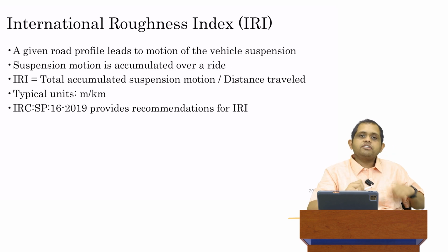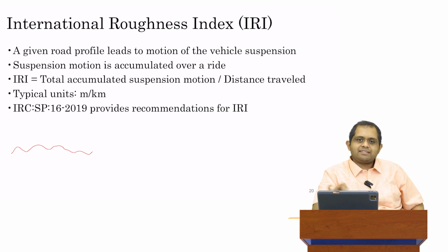The International Roughness Index is as follows. We go out in the field and using a certain instrument, which is called a profilometer, we get a profile of the road. Now, what I'm drawing here is a highly exaggerated version of the profile. This distance is actually going to be in the order of 1 or even less millimeters. So it's highly exaggerated what I've drawn over here. But using the profilometer, you can get the profile of the road, or the roughness of the road, to put it in a different way.